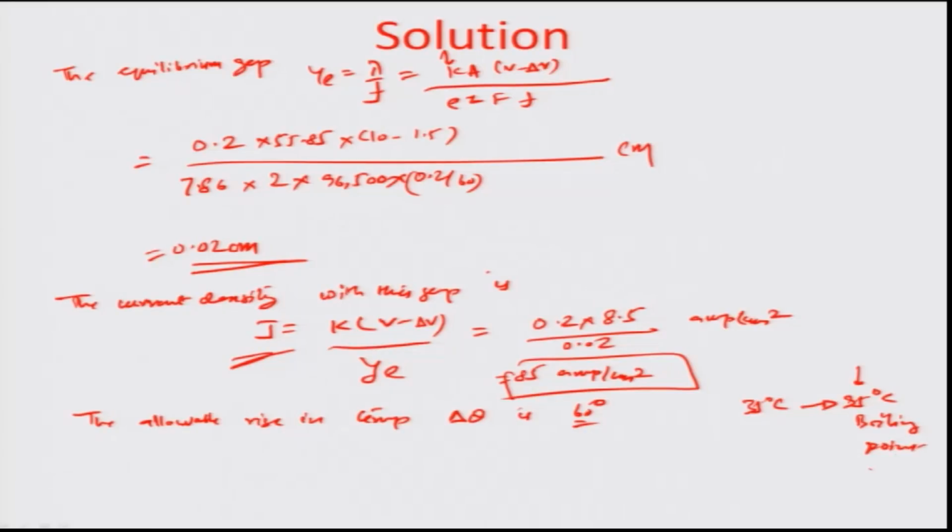So, we do not want to surpass this point, because then the finish is lost completely because of the two phase electrolyte coming into the work zone. So, delta theta allowable is about 60 degrees in this particular case. So, this is the condition for flow design.